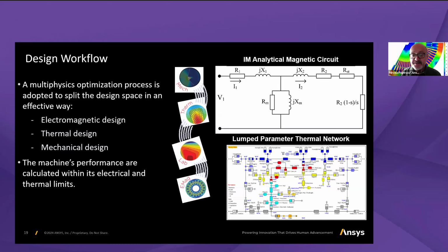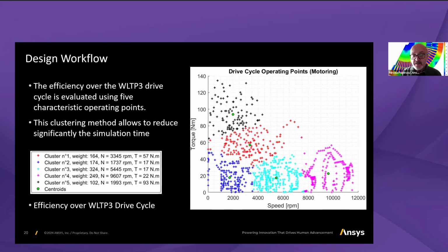stator resistance. Having in mind that at high speed, both R1 and R2 will suffer from skin effect, so will be variable with frequency. Obviously, more is the case for the rotor resistance, but as well the stator resistance, having in mind that this was manufactured using hairpin winding.